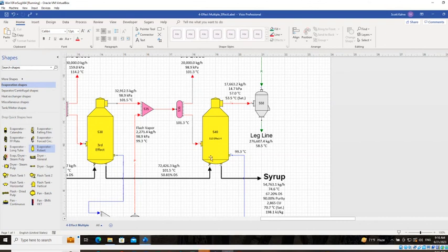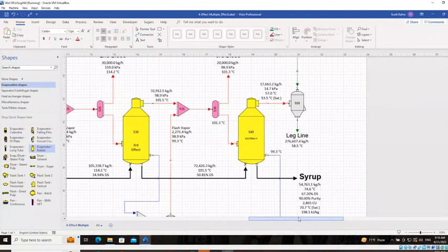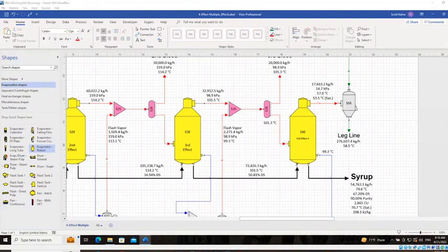It's okay, clear, thank you. Because the delta T is normally known for sugars because the heat transfer surface can be determined based on delta T by taking the given heat transfer coefficient and the heat load. Or you can determine the heat transfer coefficient based on the heating surface and the heat load. So the formula still is existing and delta T is known for sugars. The only thing missing is to show it as a parameter in the legend. But it is okay, it can also be done like this. Yes, thank you. Okay, thanks for the question. All right, so let me look at my list here.